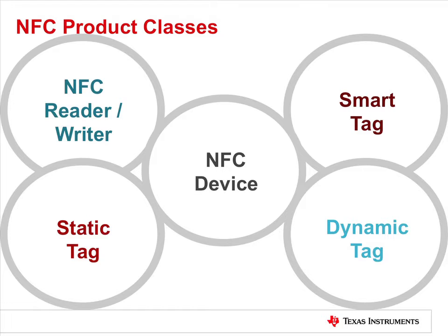But if you have a look at the different end equipments, not each NFC product in each end equipment has to support all operating modes. For example, a door lock system does not have to emulate a card transponder, and for an NFC transponder in a poster, you do not need a device which supports the reader-writer mode. Therefore, we have more dedicated devices depending on the application requirements.